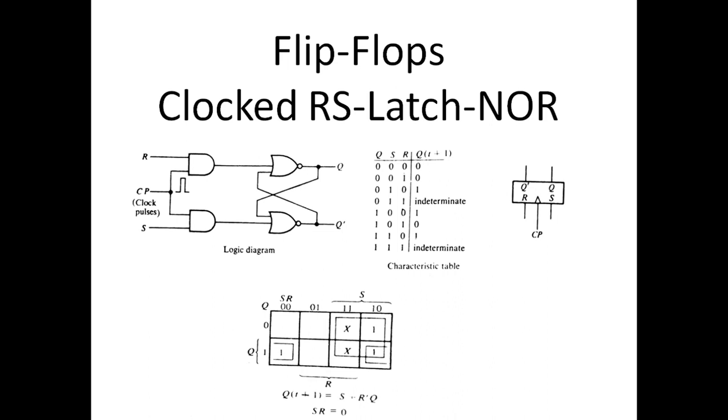That means SR can only be 1 when S is 1 and R is 1, and that is not allowed. SR must not be equal to 1. That means SR is always equal to 0, and logically that means one of the inputs S and R must be 0.